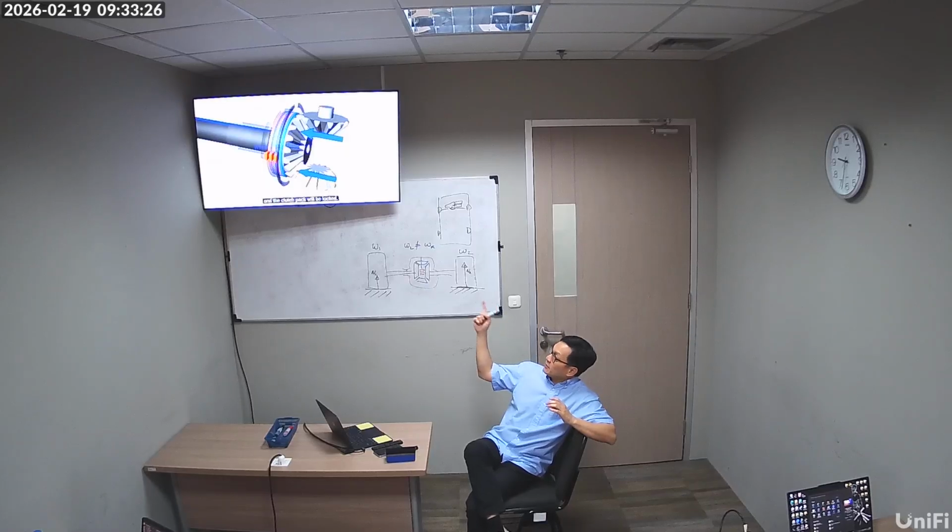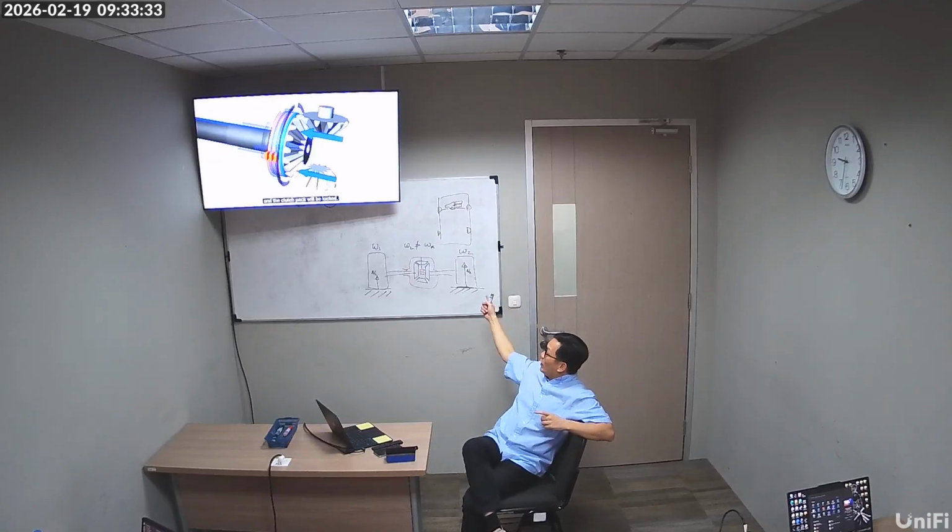Moves freely. Well, actually, this thrust force will be greater at high speed. So, when one wheel spins faster, it's going to press the clutch pack on that side. Okay? So, the speed is actually going for our advantage. So, there is the effect of the speed to the outward motion to this clutch pack, which then presses it the way we want it, right?